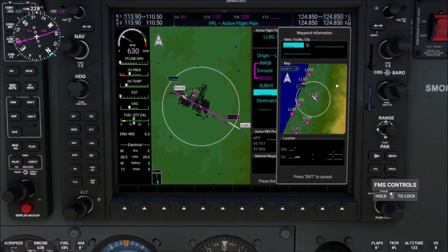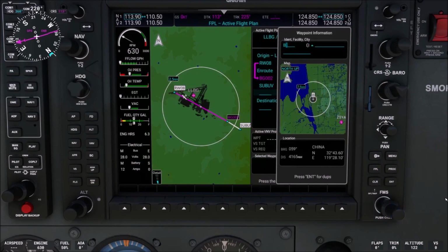We continue. And next is BG040. Here it is again, the new window. Please listen, something important. Use this system, not this one here. If you press here, you can type. If you press here, you can as well type. But you don't have any keyboard when you are inside the Skyhawk, isn't it? There is another reason. If you press here, sometimes it appears also an additional position, position number 6. Or if you have, let's say, 4 letters or numbers, position number 5. And then you can have a mess. So please use this boring system and don't use the keyboard pressing here, okay? Just to let you know.